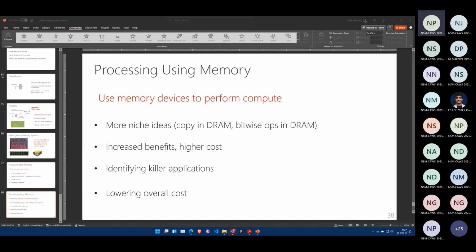Since all of the DRAM is not really useful, is refreshing all of the cells required? Can we not identify which cells are currently used and refresh only those cells? Great idea. I think it has been explored to some level in some research papers as well. I would suggest just doing a Scholar search for DRAM refresh, and you will hit a bunch of different papers which have explored ideas. And I think we are yet to hit ideas that are elegant in the space.